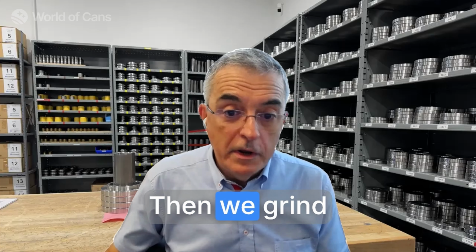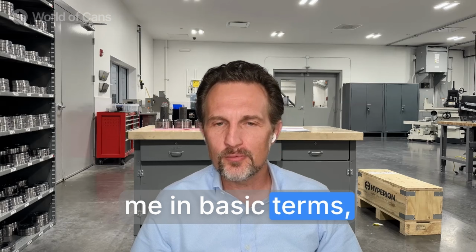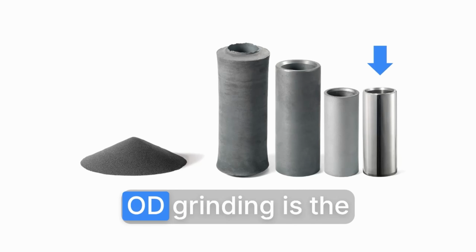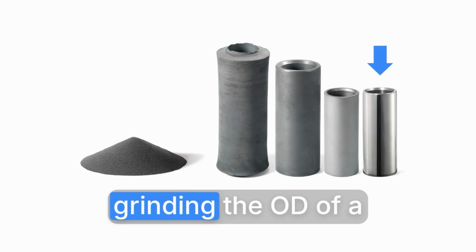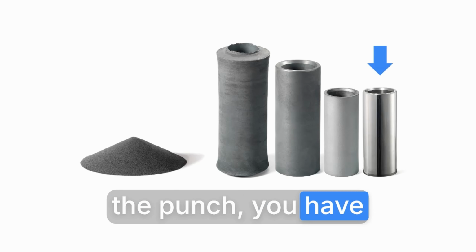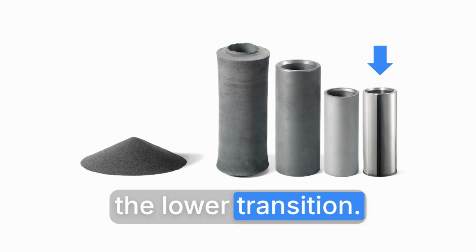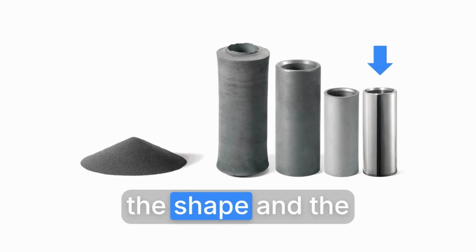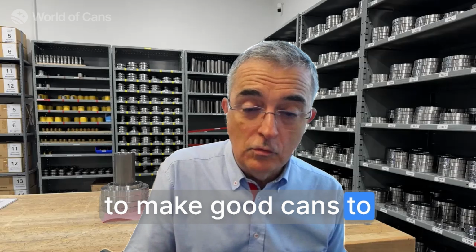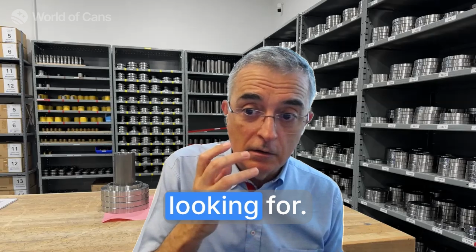What happens next? Then we grind the parts. Can you explain to me in basic terms what is OD grinding, what is ID grinding? Well, OD grinding is grinding the OD of a punch, the outside of the punch. You have the step, the upper step, and you have the lower transition, and the position, the shape, the geometry are critical to make good cans, to achieve the lightweight cans everybody is looking for.